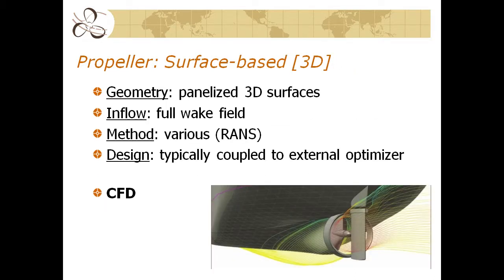And then true surface base, panelized 3D surfaces, CFD, of course, full wake field. There's a variety of different analytical methods, RANS being probably the most popular of it. But when we talk about design, it's typically coupled with an external solver. So you'll use a tool like modeFRONTIER or CAESES or something like that to drive the CFD analysis to actually solve for an optimization in this.